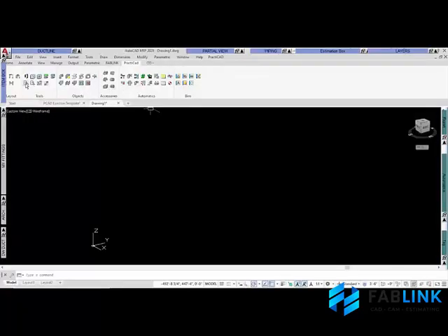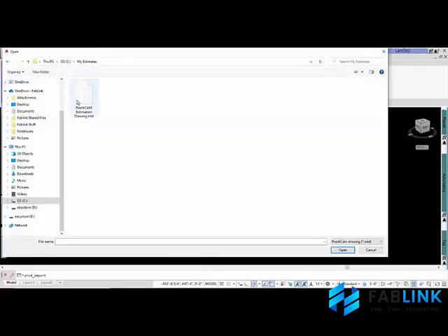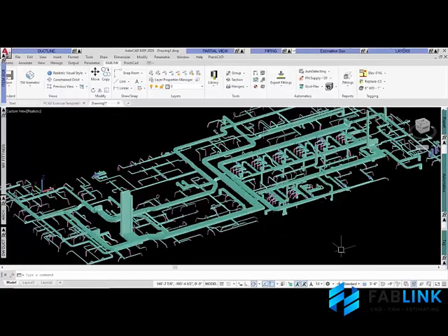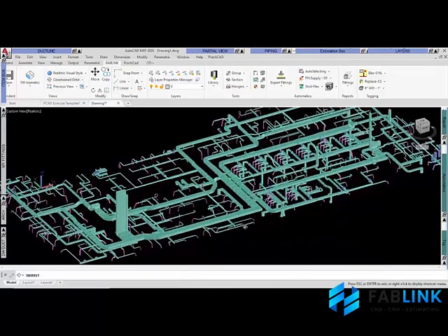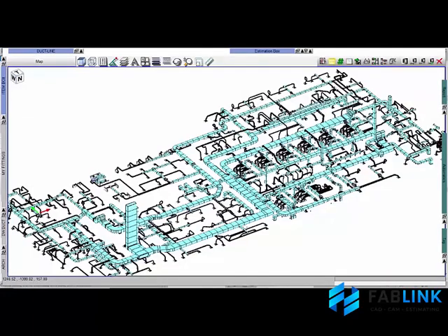Next, we will go directly into PractiCAD and hit the import button so we can import this file directly. This way, if we got the job from our bid or estimate drawing, the drafting department can simply continue using that drawing instead of redrawing the same thing. And this is not just for AutoCAD. As you can see here, the same MLD file will be imported into MetalLab's PractiRev product for Revit.